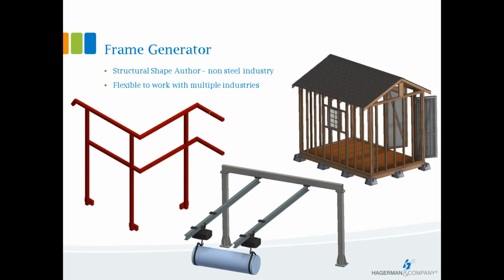So what can the frame generator do? Well, you've got the steel industry, like I mentioned, for handrails and framing and I-beams and things like that, but you also have non-steel or non-metals industries it can get into a little bit. Previously, I mentioned that you don't want to model up anything that's like a large structure, but smaller structures are certainly feasible. You've got things like storage sheds and lean-tos. The storage shed that's in my own backyard, I modeled up with Inventor Frame Generator. Right now, I'm actually working on redoing my back deck and doing the same thing, using the frame generator to lay out all the pieces, get cut lengths, get an overall build plan going, and I'm using the shape author to publish in 2x4s, 1x3s, 2x6s, things like that, things that are not part of the standard content center shape library. It's flexible to work across multiple industries.